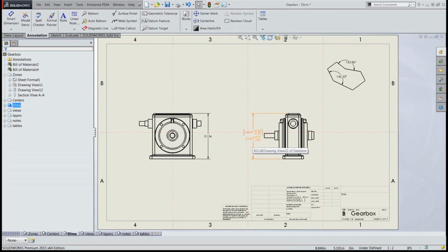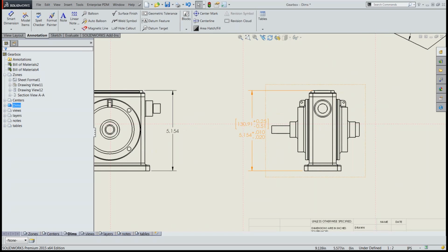Now they have the tolerancing rounding. What this does is allow you to set limits of the secondary unit's values to fit within the tolerance range of the rounded primary unit. So sometimes when you round, if it rounds up or down too much, and you actually do a conversion of it, it doesn't match the primary units anymore.